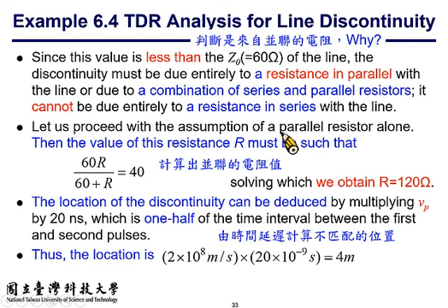So we know that it's in shunt configuration. So you can calculate the shunt resistance using the equation you have with circuit theory. All right. So you can solve the shunt resistance as 120 ohm. Okay. And the other problem that we can solve is, where is the discontinuity?